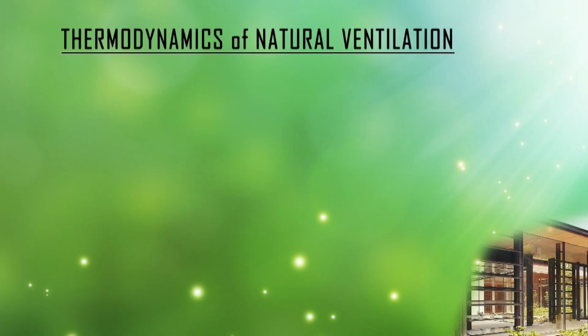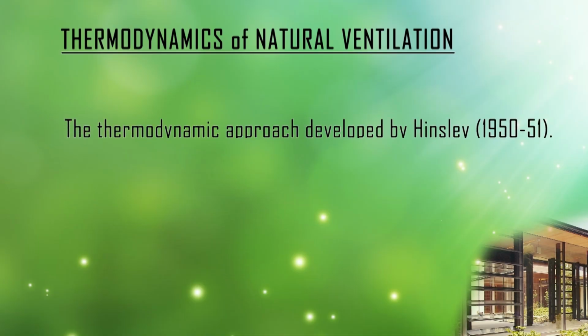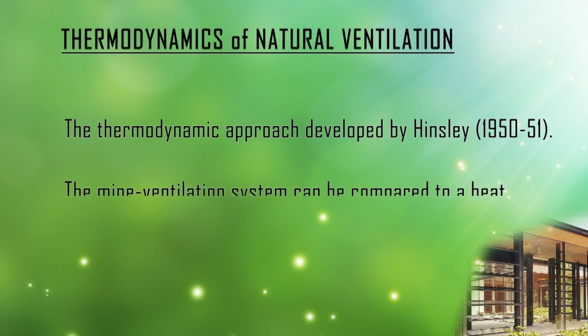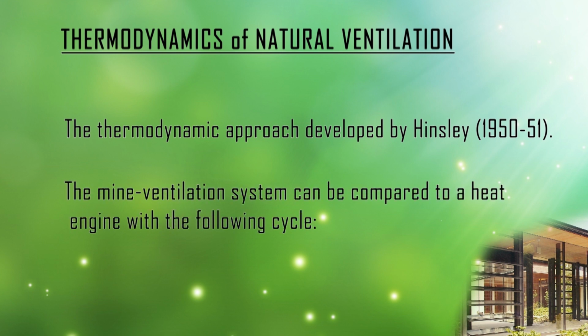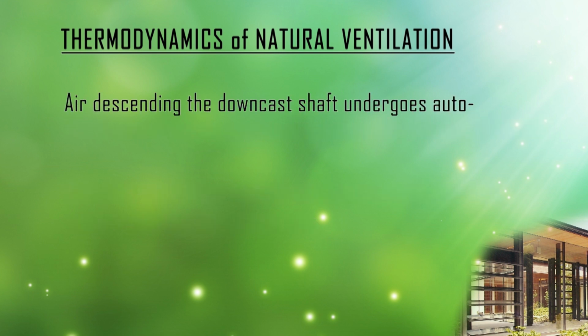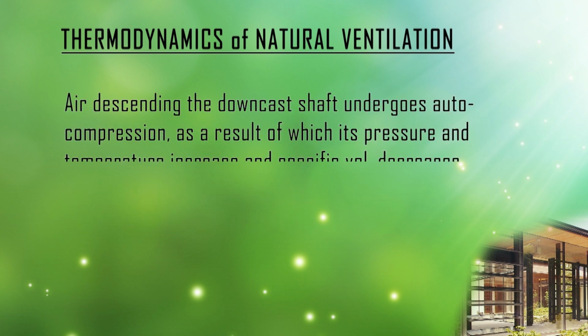Now, come to the thermodynamic approach of natural ventilation. This approach has been developed by Hinsley in 1950-51. According to this, the mine ventilation system can be compared to a heat engine with the following cycle. Air descending the downcast shaft undergoes auto compression, as a result of which its pressure and temperature increase and its specific volume decreases.